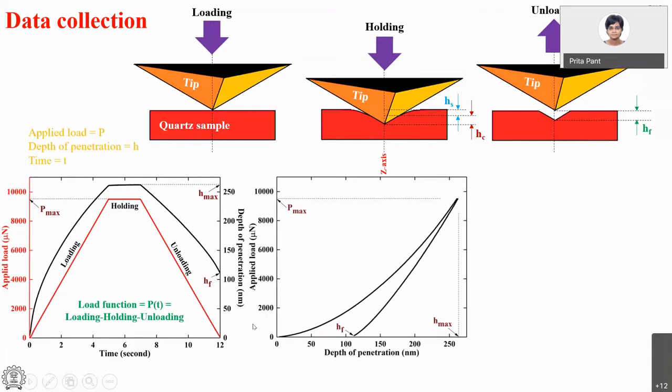If I plot now, on the left, what you saw is load and depth as a function of time, and what you're seeing now is load as a function of depth. I keep increasing the load, the tip goes deeper and deeper into the sample, and then I unload, it comes back to some final depth HF. Okay, these terms need a little bit of getting used to.